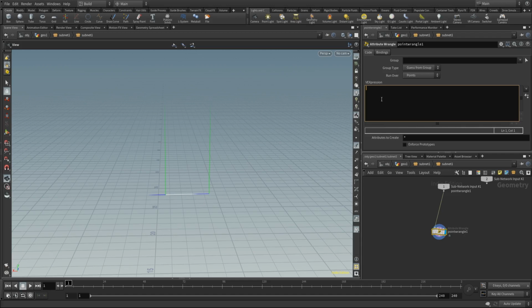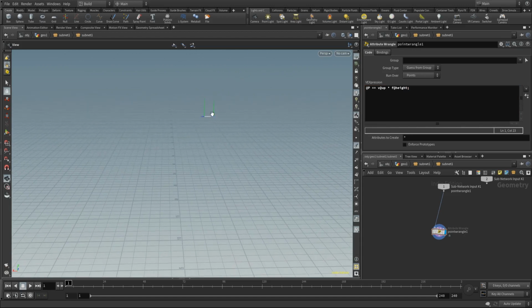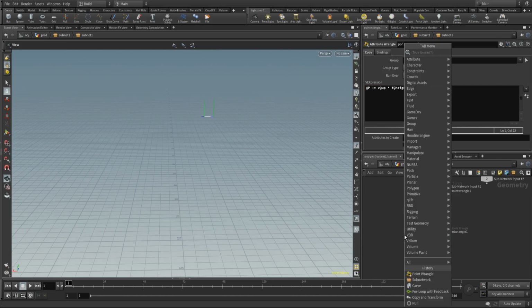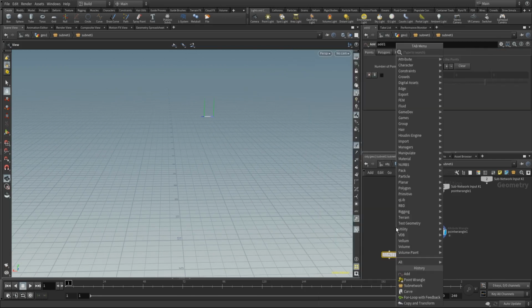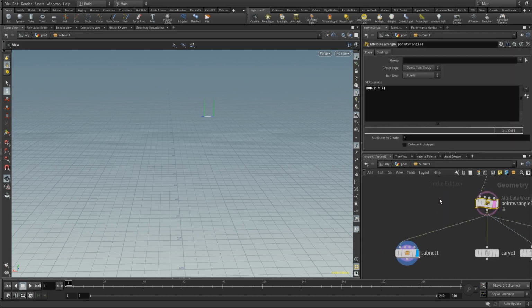And we can do this by typing the original position, and we're gonna add to that the up vector multiplied with the height. F at height. There we go. And if we do this right now, it is transformed up, or in towards the up direction. And if we now place an add node and a merge, we can create a cool plane out of this. Nice little primitive.